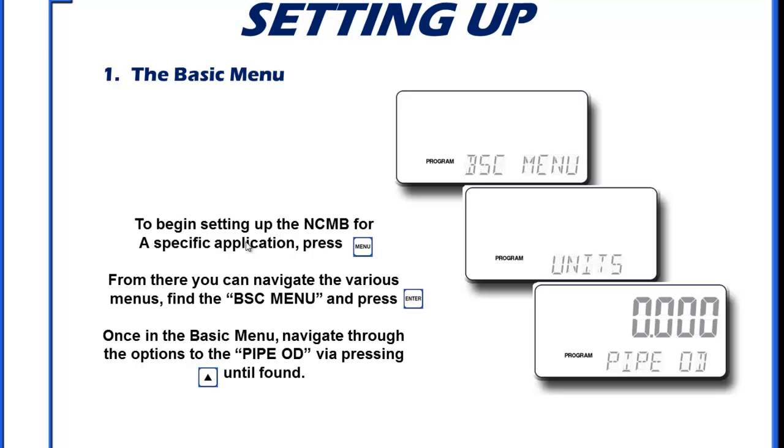After that, we need to go in and specify the pipe information. Now, we have pipe ID, and you can scroll once you get into the pipe OD, pipe outside diameter. You need to specify the real pipe OD. Every manual is included with an ANSI pipe chart guide, and if you have a 6-inch pipe, you don't punch in 6 inches. You remember the spacing of the transducers we just saw and the trajectory that needs to be calculated. We need to have real numbers when we program a transit time flow meter. So you need to use your ANSI pipe chart book to put your pipe OD and ID in there.